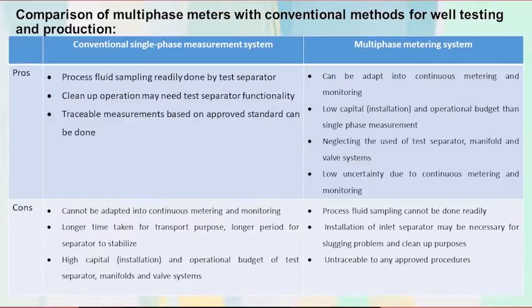And further disadvantages is sampling of the process fluid is not readily available. An inlet separator may be required as a slug catcher and for well cleaning purpose. And multi-phase metering is not traceable to any accepted standard.